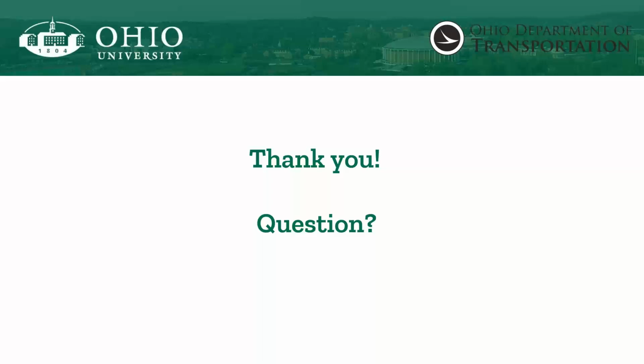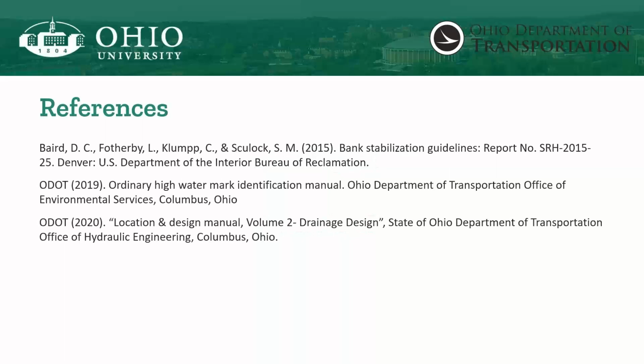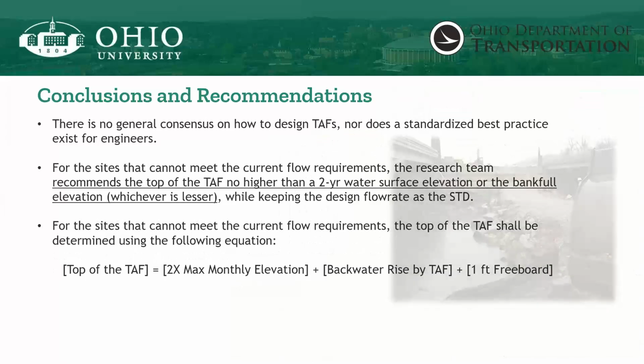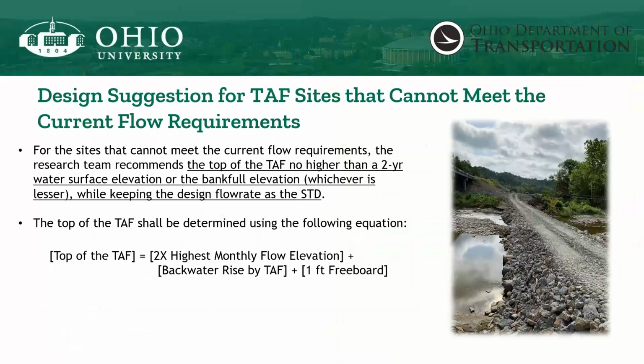When we talk about 2D, we're talking about actually creating a grid and discretizing the entire geometry. Once we've discretized the entire geometry, we use what's called a finite volume method, which is similar to finite elements, but slightly different. We calculate what's going on in each one of these grids, and make sure that each one matches up with the grid next to it.